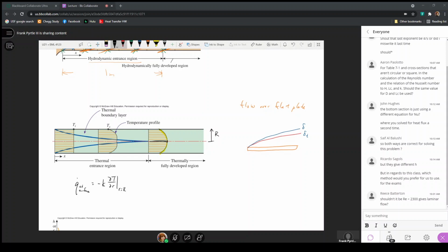So that says the heat transfer is occurring out. I'm trying to draw it as a flux, out of the fluid and into this surface. But that heat flux at the surface would be minus k dT/dr. So as we move from r equals 0 to r equals capital R, the temperature is decreasing. So this heat transfer rate will be out of the fluid and into the surface.